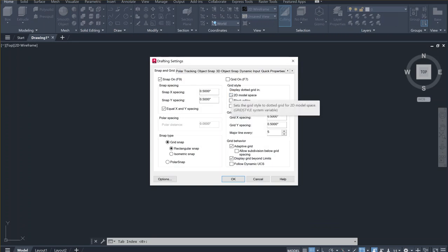It gives your cursor the ability to stop accurately at every so many inches. You can set it to 1/8 of an inch, 1/10 of an inch, 1/16 of an inch, 1/32 of an inch, or in some cases other values. Now, what is the advantage of it? The advantage of having snap on is that for basic dimensions like 1 inch, 1.5 inches, 3 inches, you don't have to type numbers. Instead, the cursor will show you immediately exactly how much it is, and it's convenient. It's called a productivity tool.